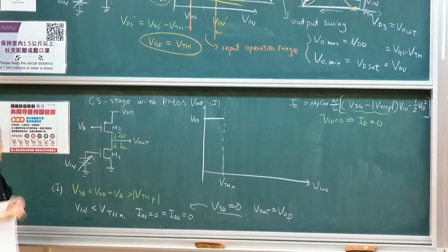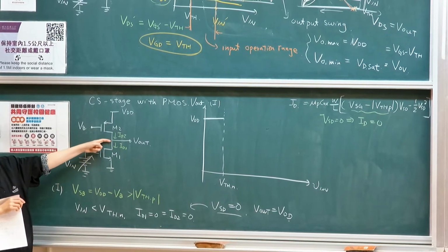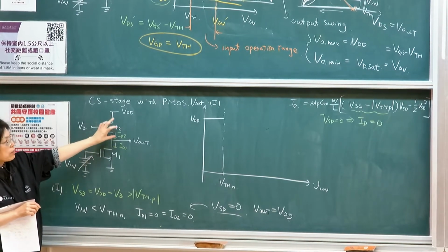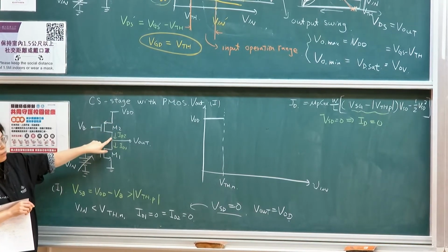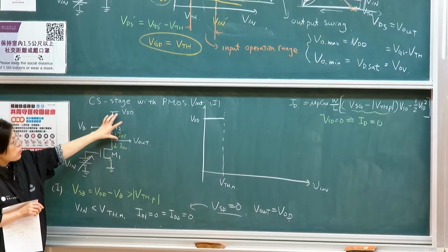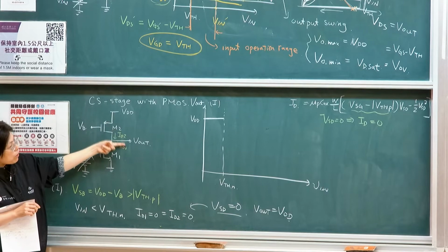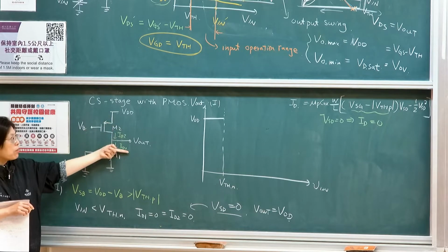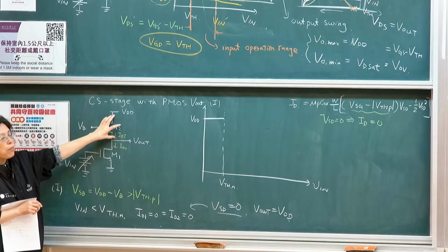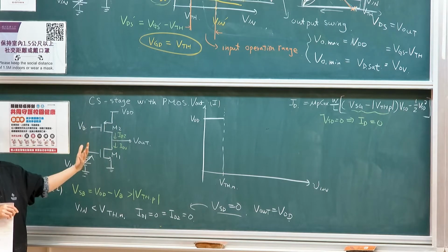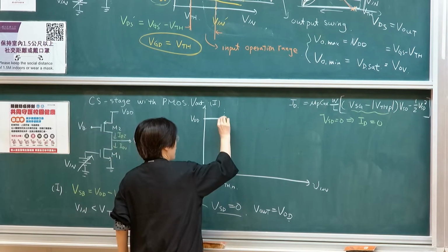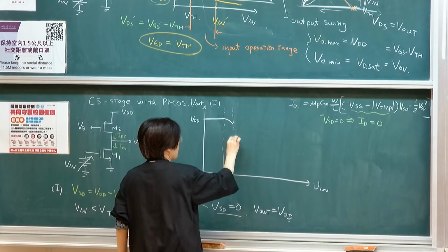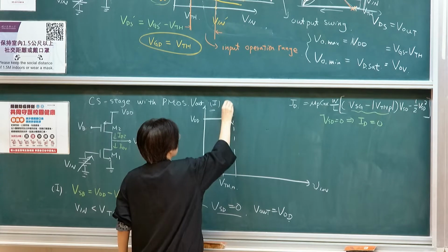Okay? So once this starts to turn on, this level is still very high. Therefore, this transistor will remain in linear region because it starts at 0. So it can only move by dropping this level; the output level is supposed to deviate from VDD, drop down from VDD to create some headroom for M2 to start entering linear region. So you then have a small little room where it goes like this. So this is region 1, region 2.